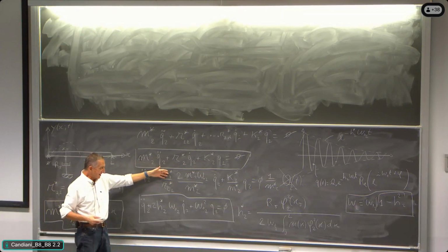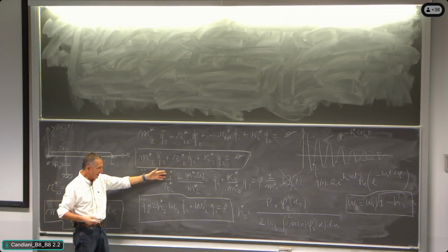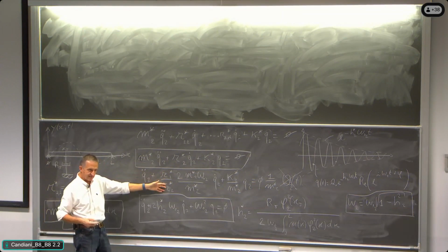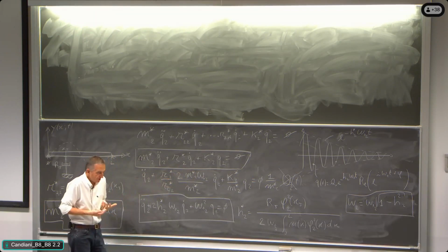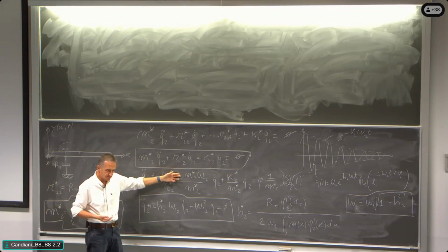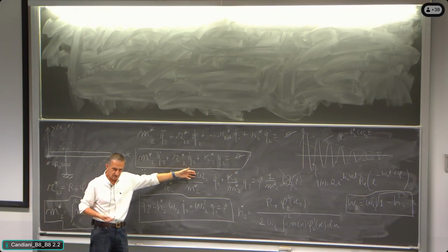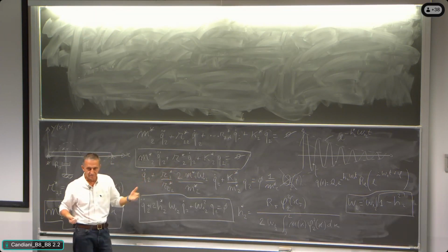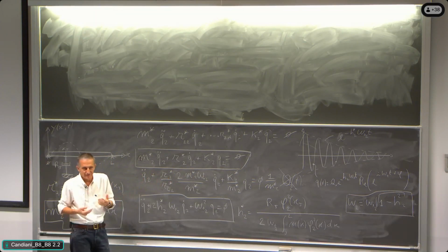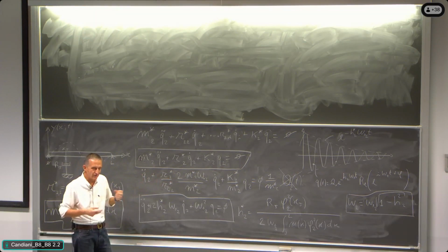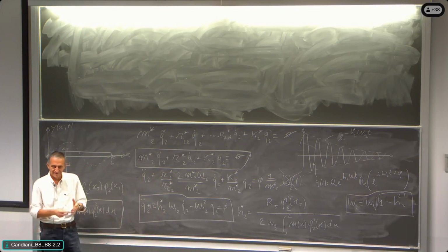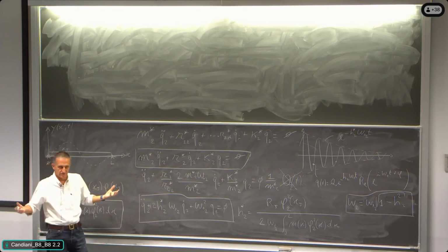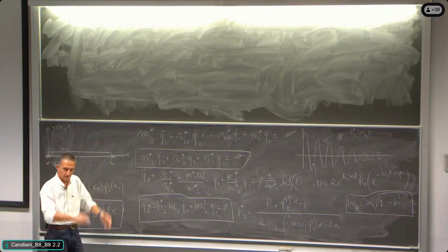So I have to divide the dimensional damping by the critical damping, then multiply by the critical damping, and we must know that the critical damping is 2 times the mass multiplied by the natural frequency. Why? Because we know it. It is not necessary that now I go into the details of why the critical damping has this value. We must know it, all right? I don't go into more detail about that.